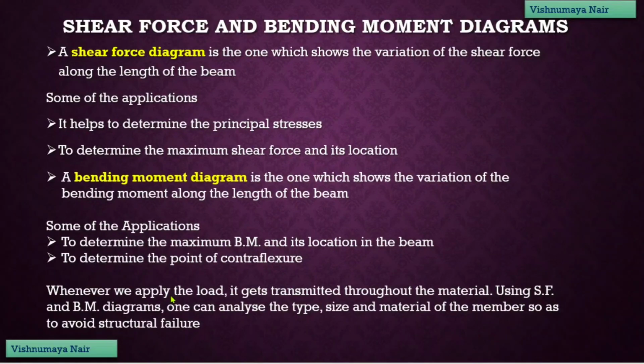Whenever we apply a load, it gets transmitted throughout the material. So, using these shear force and bending moment diagrams, one can analyze the type, size and material of the member so as to avoid the structural failure.